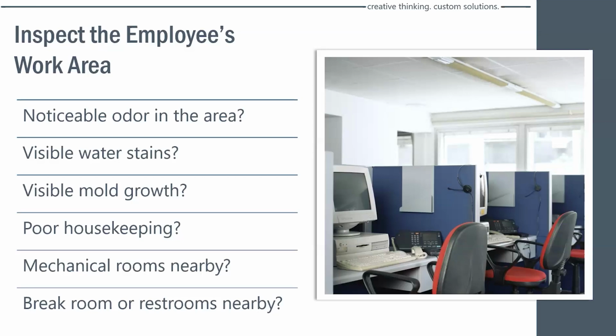So usually when you open the door to a facility, you should feel a puff of air, that positive pressure. And likewise, there are parts of a building that are under negative pressure. Restrooms, especially, are under negative pressure; usually they're exhausted out through the roof. For obvious reasons, you don't want bathroom odors finding their way into work areas. So there are a lot of things at play here. There could be printers and copiers nearby that contribute to particulate in the air.